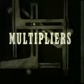Multipliers are mechanisms which can multiply two continuously changing values. We shall use this rack-type multiplier for purposes of illustration. Other types work on the same principle. The rack multiplier has two input racks, A and B, at right angles to each other, and an output rack. One input rack has a slotted pivot arm, which swings around a stationary pin.